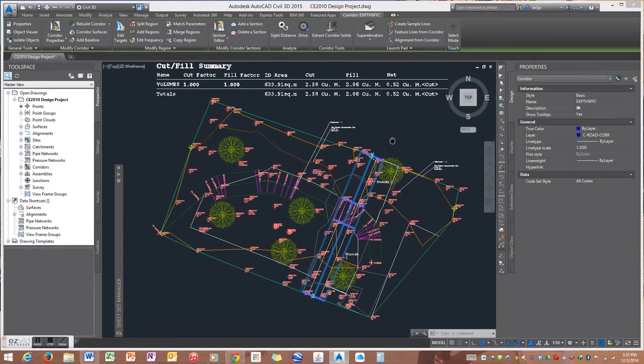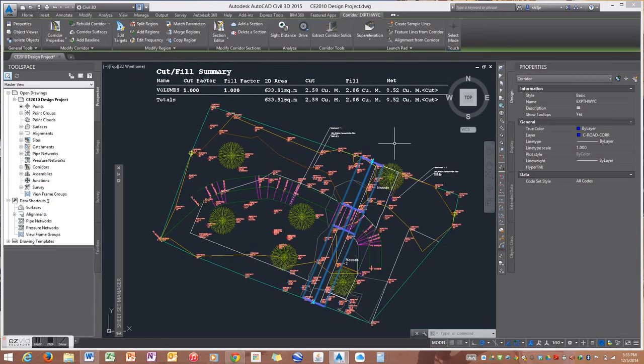As you can see, my cut fill came out very low. It was a net cut of 0.52 cubic meters. I was able to attain this by, as I said before, trial and error with the location of this pathway, and again, instead of regrading for additional stormwater management, utilizing the existing ground surface and implementing the bioswales.